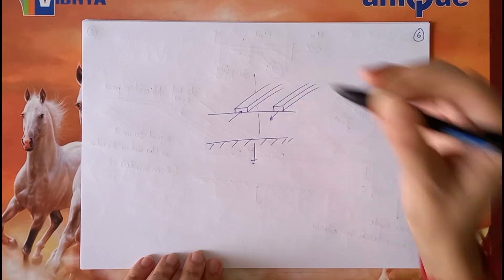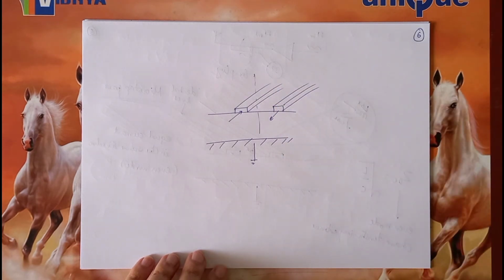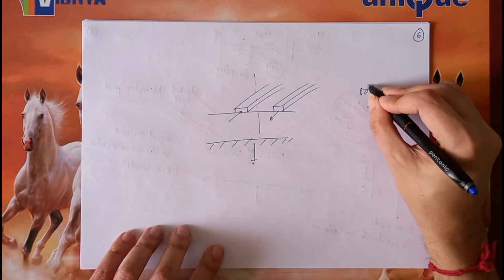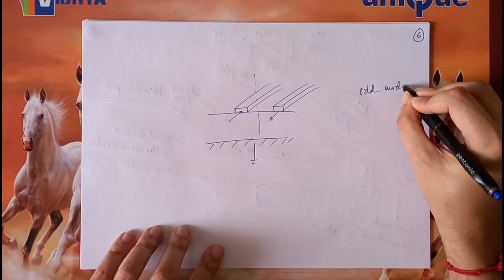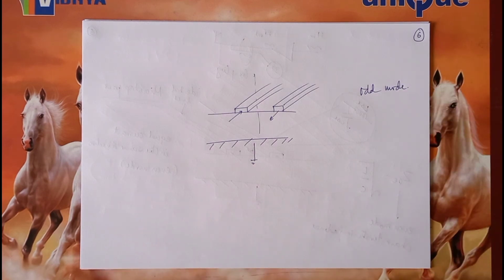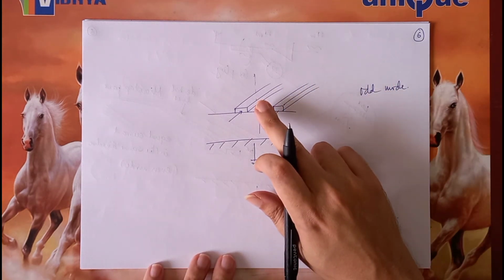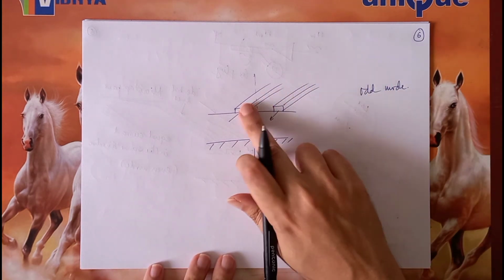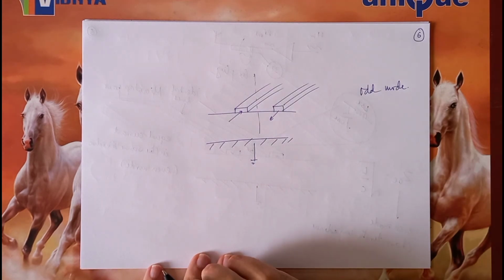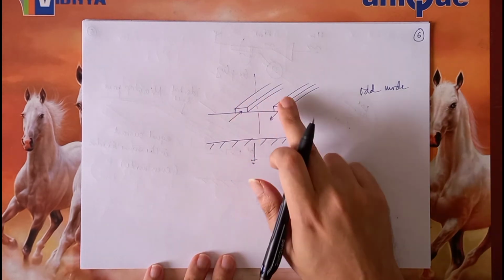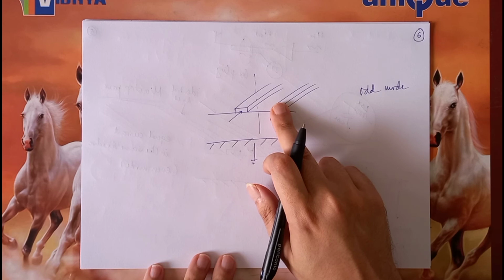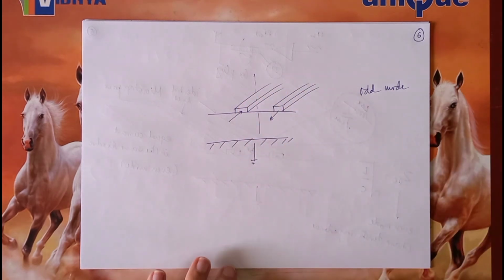So in the middle, as we know, there would exist a virtual short circuit because this is the odd mode. Now we can no longer say that these two are independent, because we saw that in the odd mode some interaction is actually happening between the two.